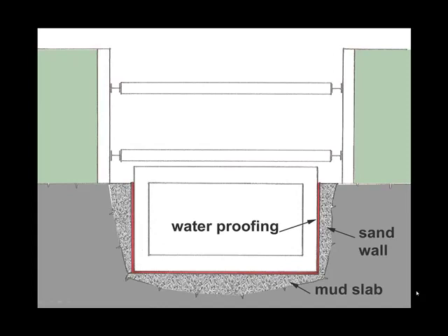Now, how do you accommodate this area which has been over excavated? We have already seen an illustration in the video of a mud slab. So after you have completed your excavation, you pour the mud slab. The mud slab is always an event to be celebrated because it means you have gotten all the way down to the bottom of the hole.